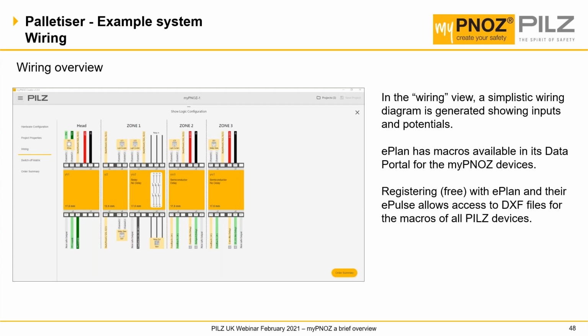Starting off at zone 1, we have all our devices. We have light curtain 1, light curtain 2, and safety gate 1, powering up the relay output. It also has start and stop signals for every single one of the input devices and a common feedback signal for the output device. Zone 2 has the light curtain and its start signal, has power supply for the unit and output signals, and then there is feedback for the two signals on the output, one of them the delayed one and one of them the instantaneous one.